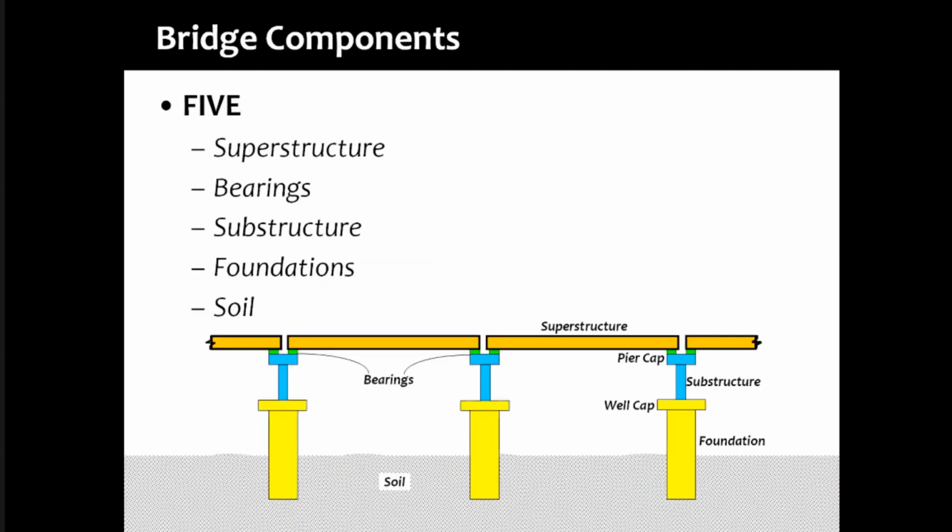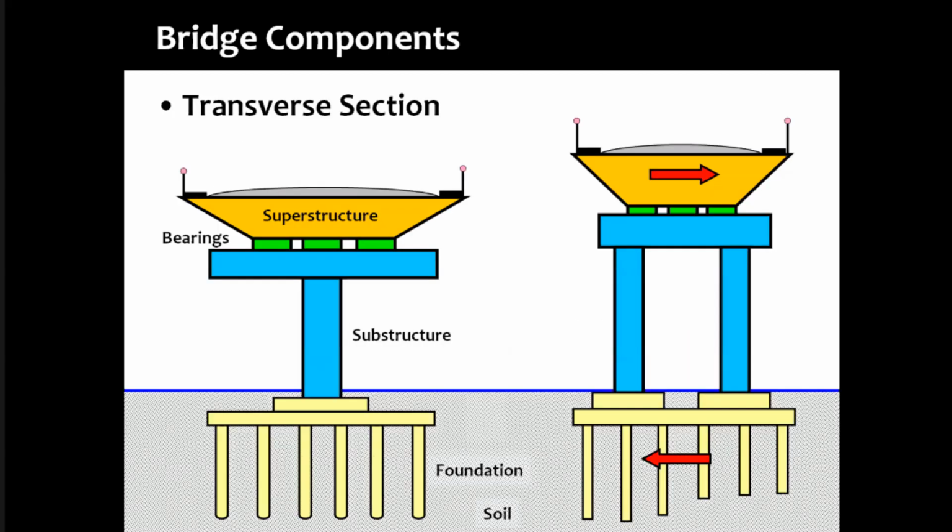So this is where I was, which I said that we are looking at 5 components of a bridge, and definitely not the superstructure. It is so stiff, the stiffness is so large that you cannot damage it under bending action or shearing action. And soil, definitely you don't want to put a bridge on weak soil. So the question is, of the remaining 3, where will the damage be? I'm trying to now exaggerate the diagrams here so that you will understand that no soil and no superstructure damage. The remaining are bearing, substructure, and foundation, right?